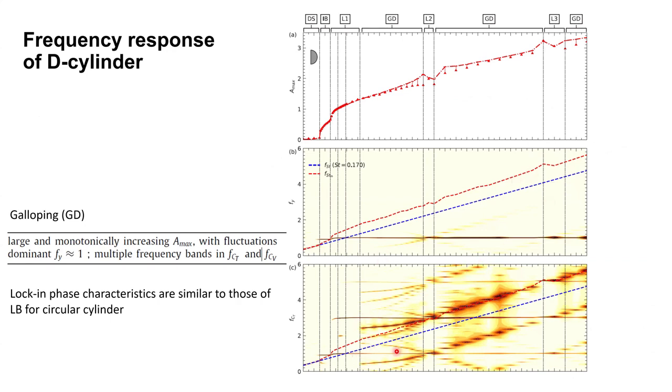So blue shows when it is stationary and we are increasing the flow velocity or reduced velocity. What is the change in the vortex shedding frequency? It's just linear. But once you have that increase by the apparent forcing, you start to have a slightly different curve, which is slightly larger than this Strouhal frequency. Now, surprisingly, this red curve agrees with what we get in simulations. I mean, the simulations which account for the motion. So red is based on simulations of the stationary cylinder, but here the contours are where the cylinder is actually moving.